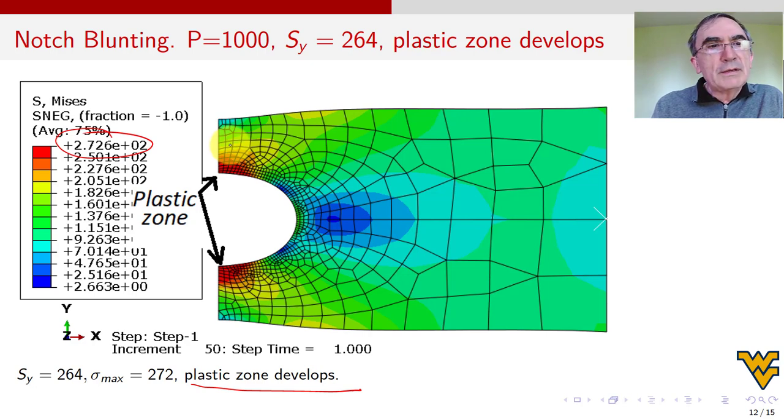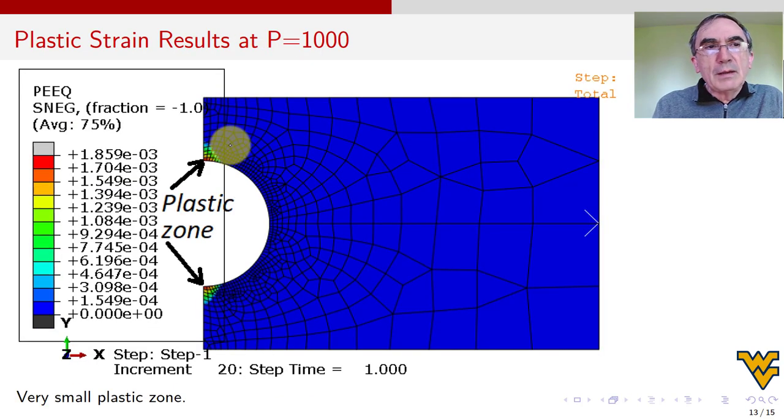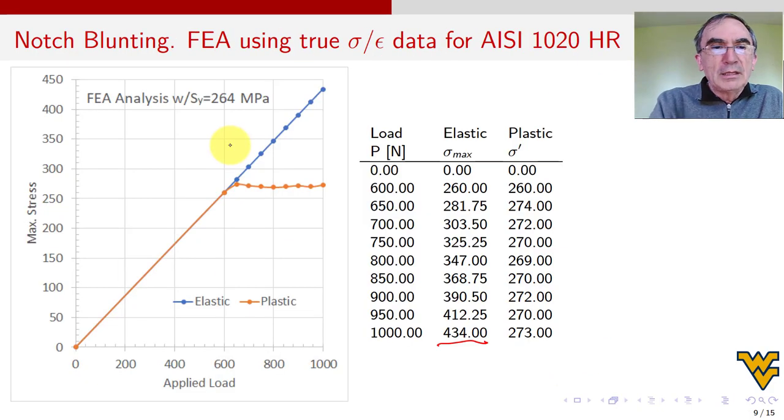All right, and of course, with the mechanics of materials, this is all we can do to calculate the stress, but with the finite element method it is fancier, so we can do other things. For example, we can visualize in a contour plot the plastic strain. How much plastic strain do we get? Okay, so the plastic strain will be, I'm hesitant to go back, but okay, I'll go back. Plastic strain will be like this. If you put here a stress and instead of load, you put strain, okay? So it's going like this.